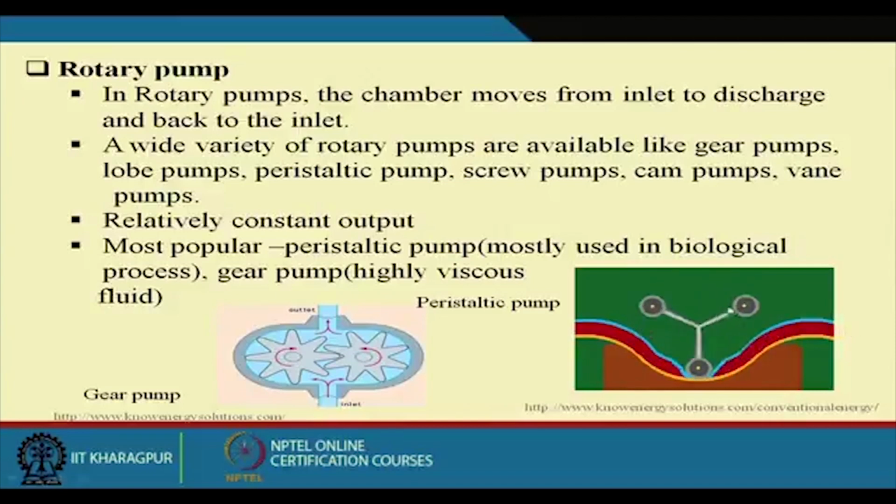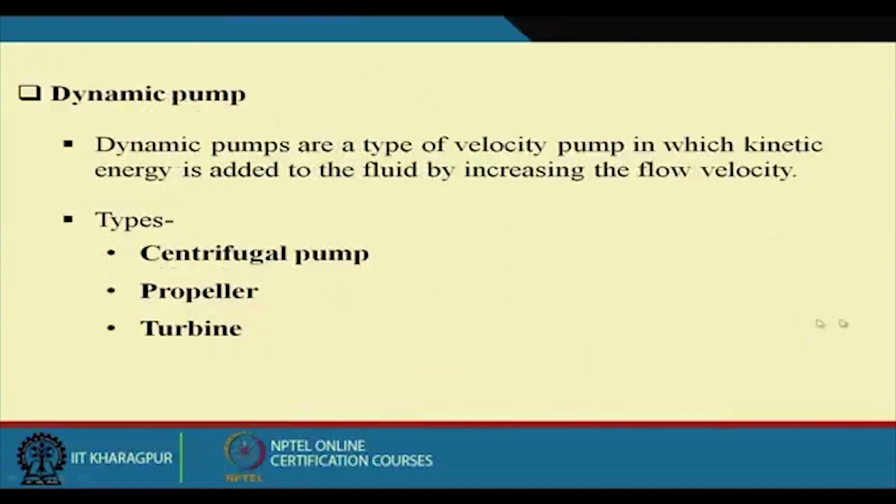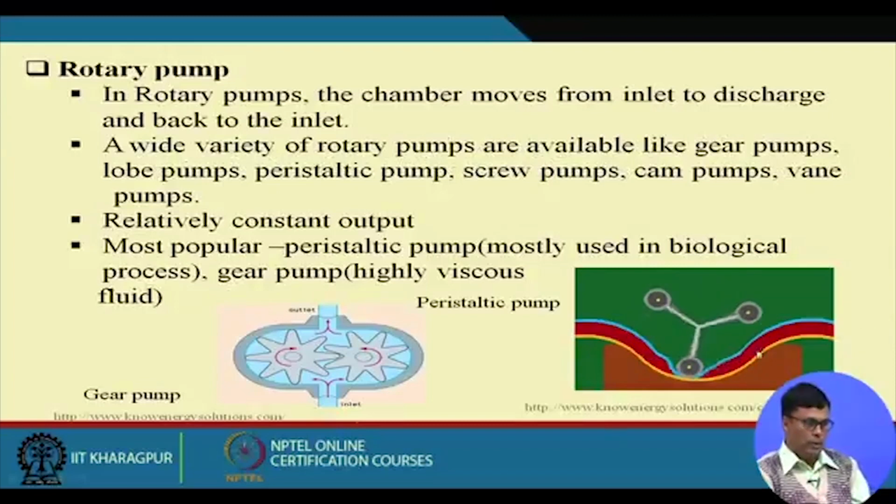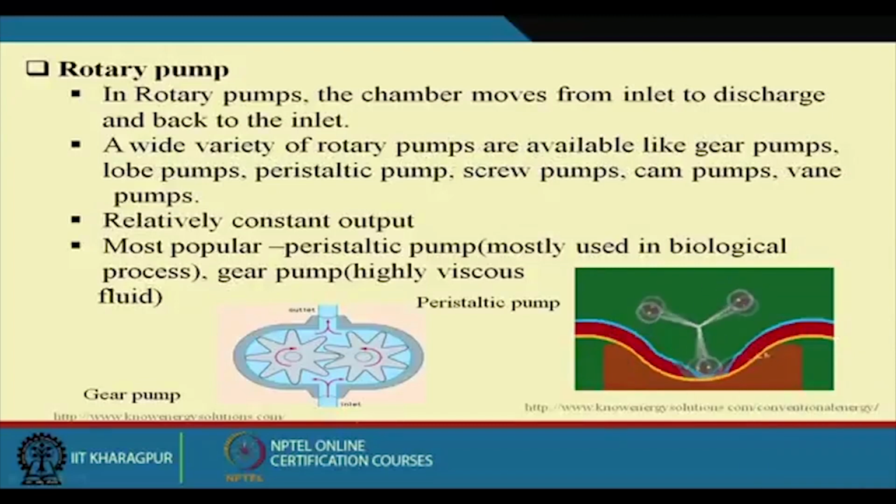Now, you can see that when this shaft rotates, the roller rotates, and then it drags the liquid this way. Can you see it? It drags the liquid from one end to the other. So this is how it works, and when you do this, all the material will remain inside the pipeline, inside the tubes. So no way will the air come in contact with this liquid. So the sterility of the system can be maintained 100%.